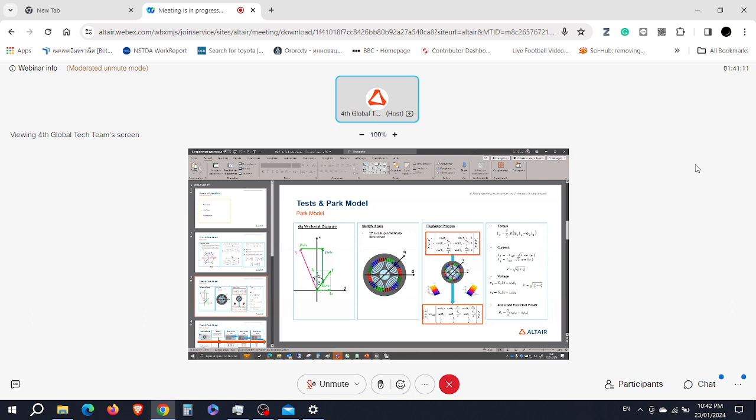Okay? Then, if you have seen the DQ vectorial diagram of the permanent magnet machine, you will see that it's really different from this one. Because first of all, we don't have back EMF produced by a permanent magnet. But we have this kind of back EMF produced by the reluctance of the machine, mainly the inductance of the machine.